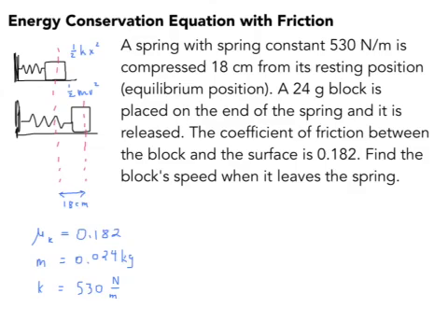So really we're just transforming some spring energy into some kinetic energy. Here's how you write the equation of conservation of energy modified to contain the energy that's being dissipated by friction. We say the initial mechanical energy plus the work done by friction equals the final mechanical energy. The work done by friction is always a negative value because friction tries to slow objects down.